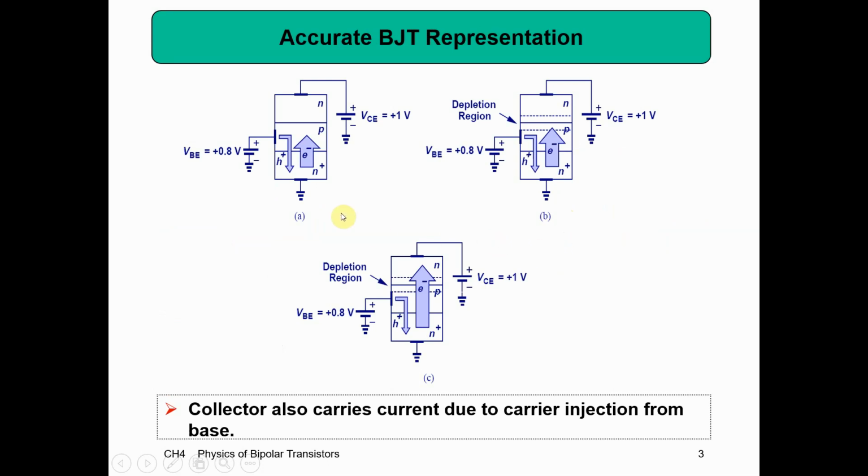So in here, you see we basically have this N region and the N region and the P region in between. And we end up getting these two depletion regions between the N and the P and the N and the P there. But we have a very narrow region in this base. And so when you insert current into here, it's controlling the two boundaries. The current going in here is controlling the current that's flowing between the two N regions. So it's like this has a little control valve.